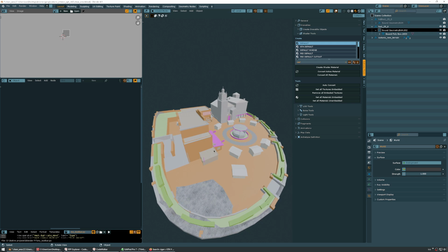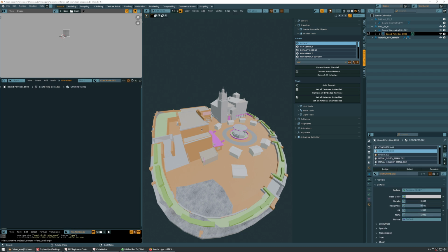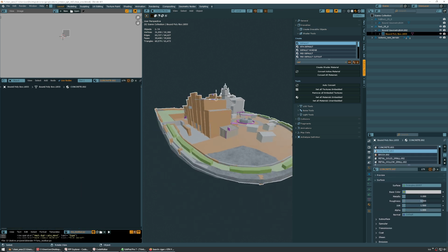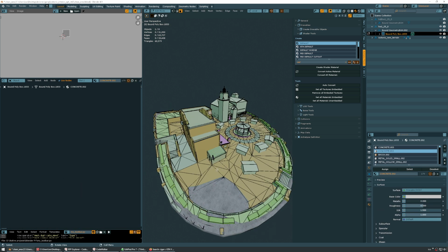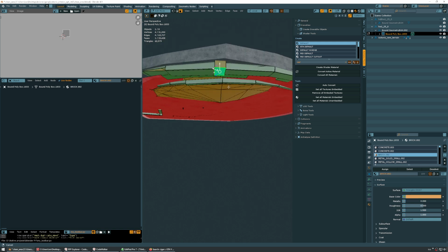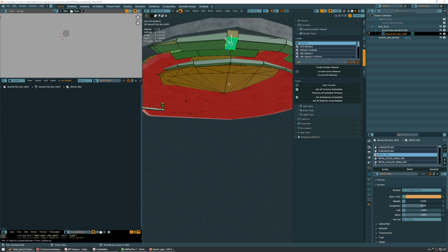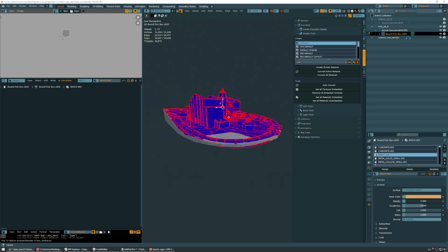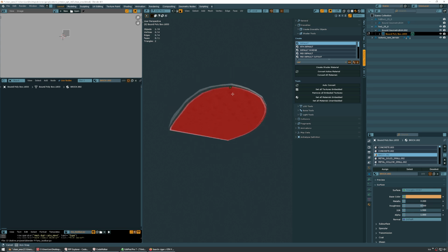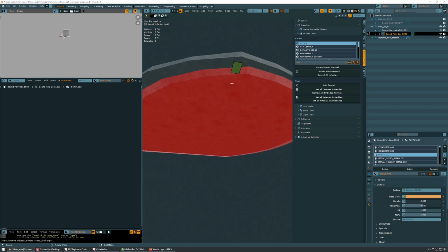If you remember from the previous attempt, we succeeded in clearing out the collision mesh, and we're going to be doing that again. It's very easy. Select a face anywhere on your collision, Control I to invert select, press delete and select faces. Now you only have two triangles, one face. That will be streamed as vanilla collisions.